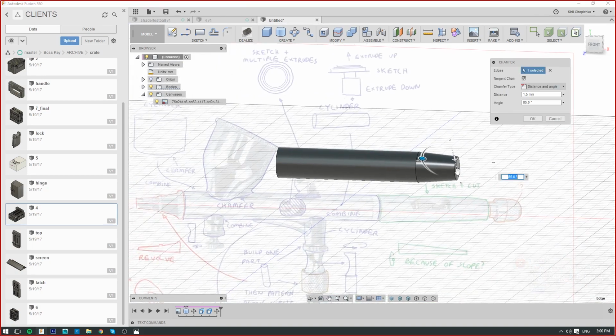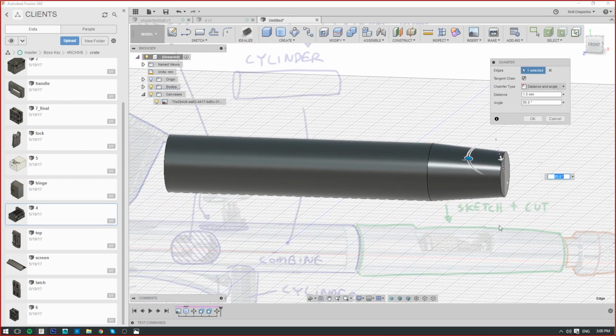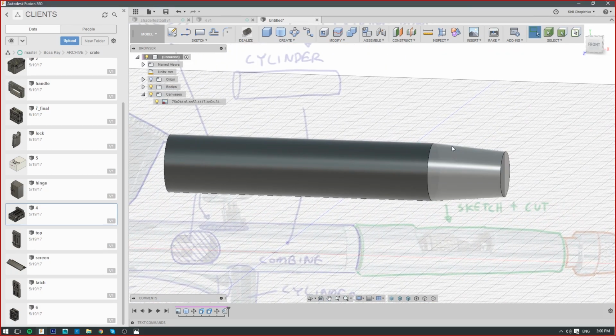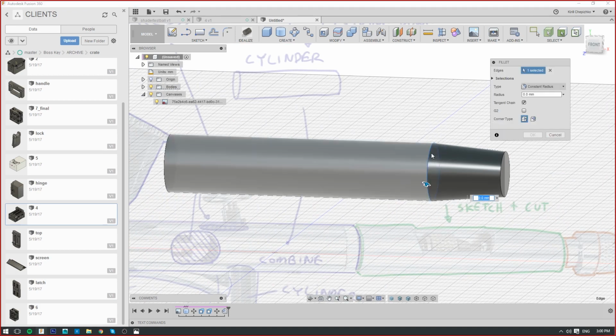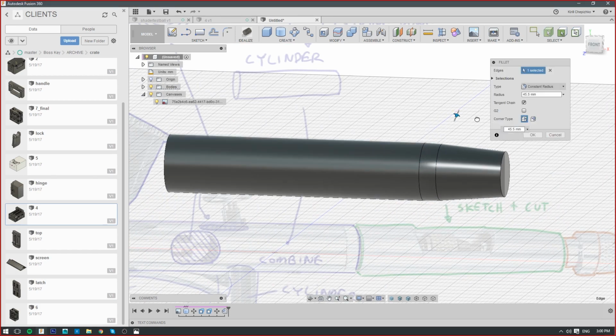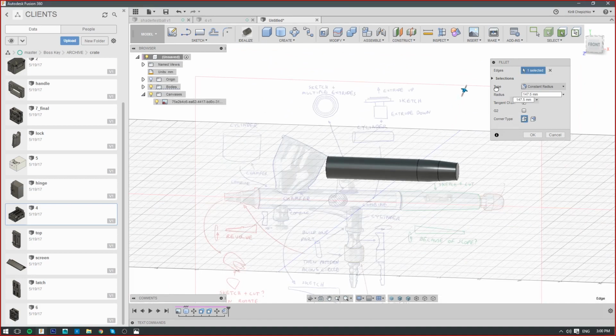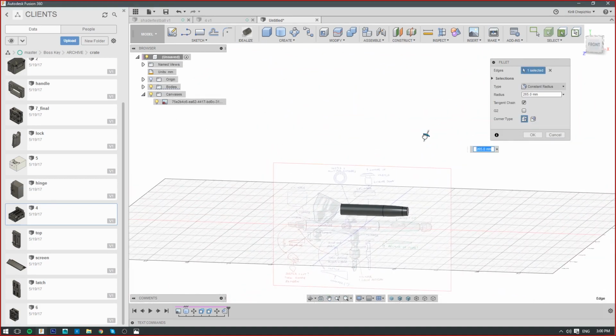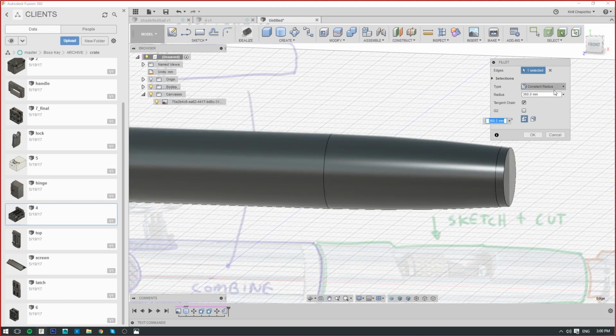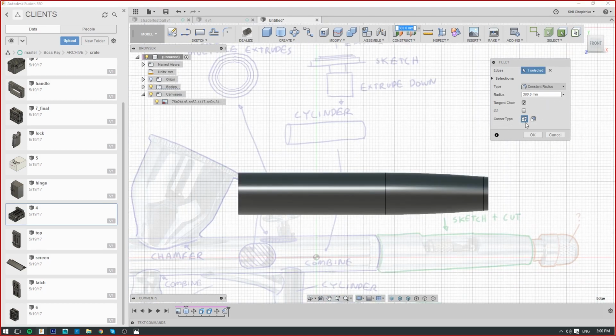It's not very precise per se, but it creates that necessary slope. And then here you can also add a fillet, and it will slightly smooth it out like that. So you get to that shape. This is just one way, right?